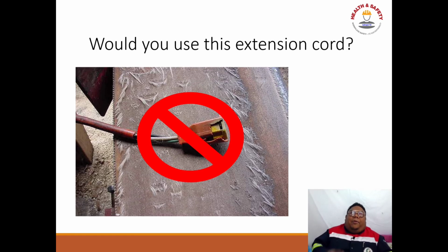And the most common electrocution, guys, especially in electromechanical or mechanical work, is during installation of posts or channels. Now, if they are using a damaged outlet like this, the open exposed live electric connection will hit the steel chassis, channels, or handrails. It can cause fatality, guys.